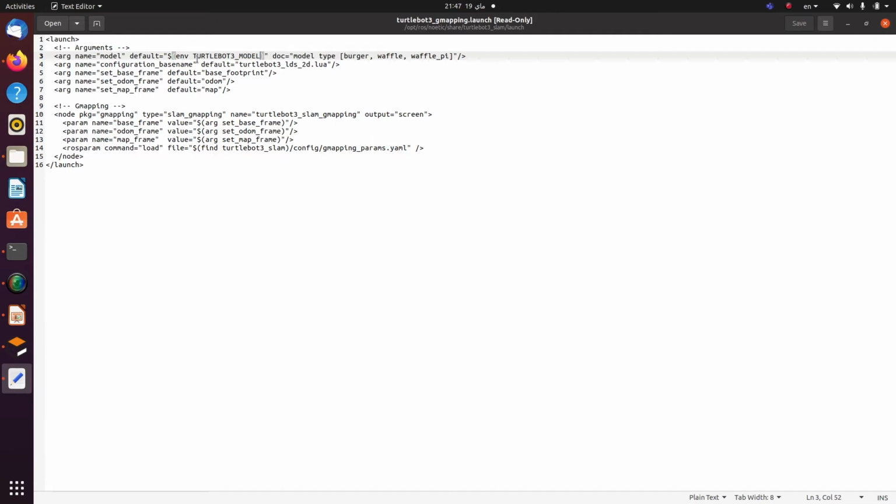So a short answer to this is that you have a LIDAR, and the LIDAR can be attached to one of several different locations on the chassis or the body of the robot. So that differs according to the mechanical design of the robot. So the location of the LIDAR and its distance from the robot origin is different for each robot.